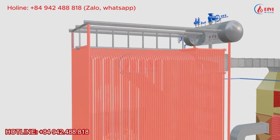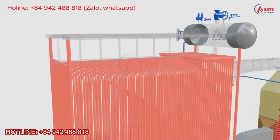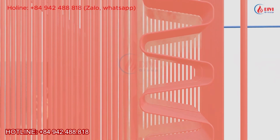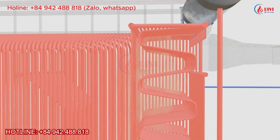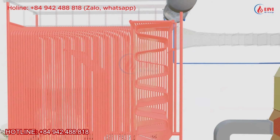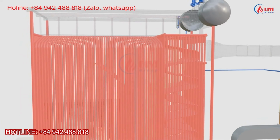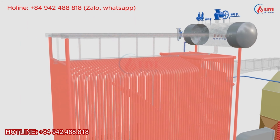Another advantage is that the water tube arrangement can be designed to provide easy access for cleaning, allowing the heat transfer surfaces to be cleaned efficiently. With properly designed access openings, individual tubes can also be replaced when necessary. Although the process may be slightly more difficult than with a combined fire tube design, tube replacement is still practical.